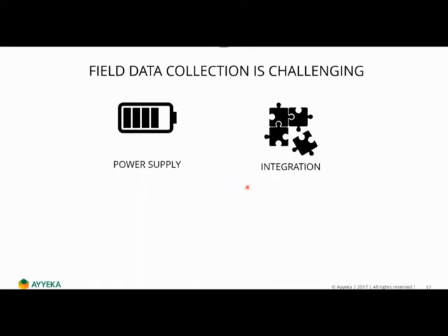All right. So sensors have different interfaces. Different cellular operators have different settings. Different SCADA systems use different protocols, and getting it all together requires a lot of expertise in different fields. And also, just estimating the power budget of the system. It depends on the communication, it depends on the sensor, it depends on the way you operate the device, and so on. So there's a lot of integration here.